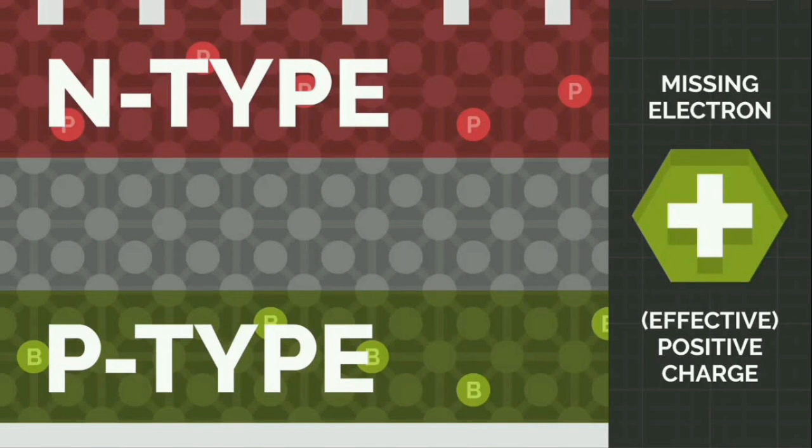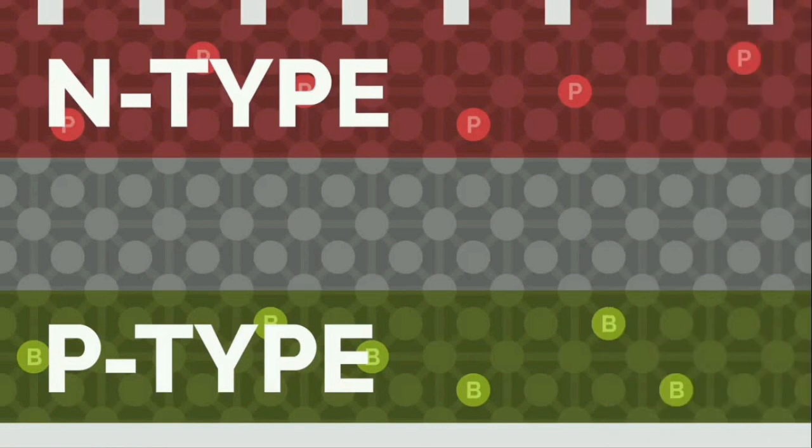The thicker middle layer has only slightly fewer electrons, making it marginally P type. Thin metal lines, typically made of silver, are printed on the top of the N layer, and the bottom of the P type layer is in contact with an aluminum plate.